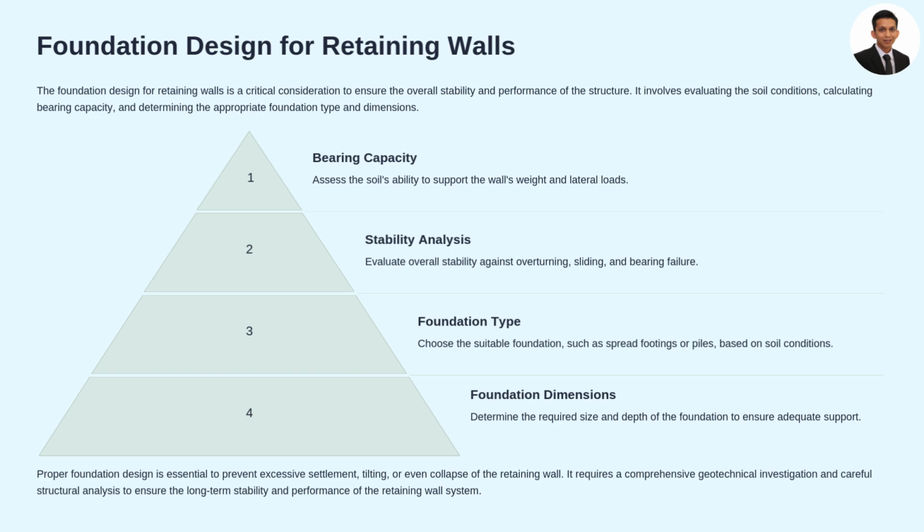Number 1. Bearing capacity. The soil beneath the foundation must be capable of supporting the weight of the wall and retained soil without excessive settlement. Tests like the standard penetration test or plate load test are performed to evaluate this.